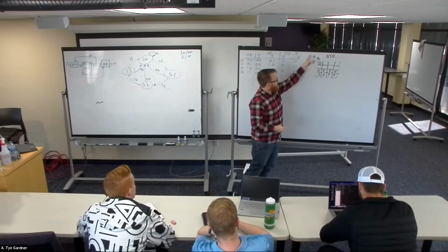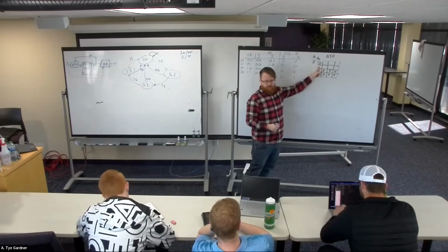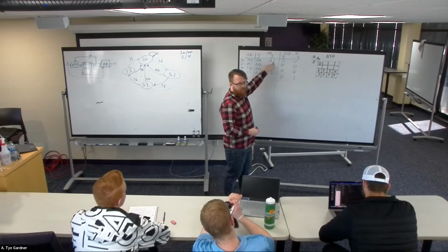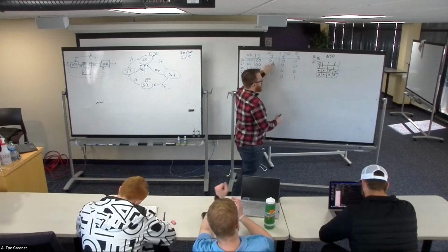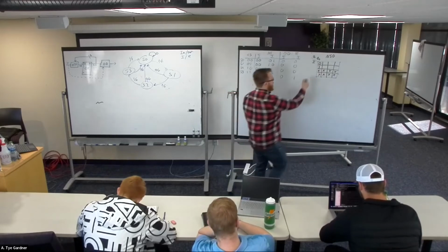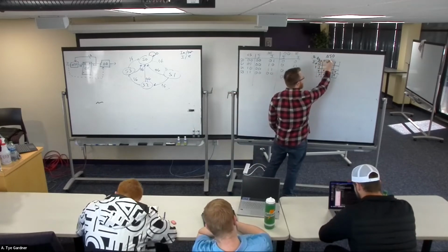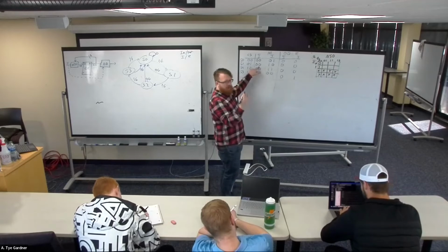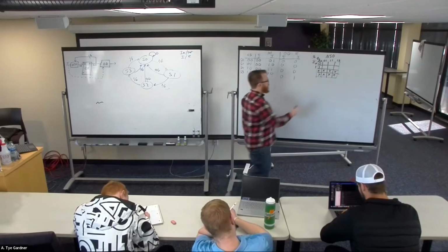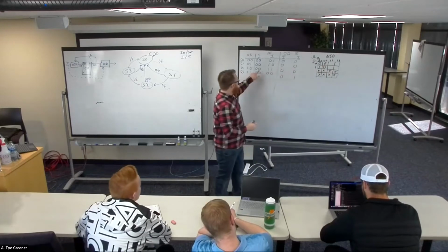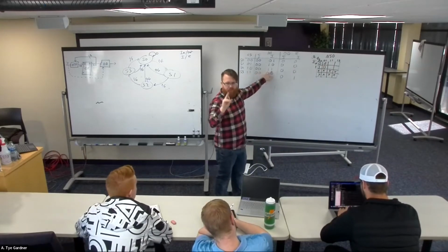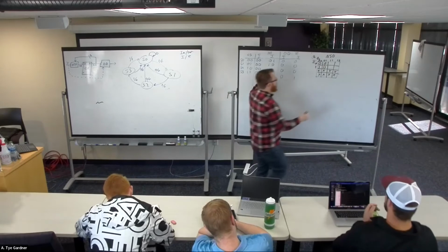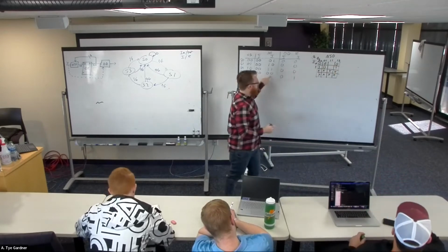Now, this square is state 0, right? For 0, 0, 1. 0, 0, 1. Right, because this is I is 0, I is 1. This is 0, 0, 0, 1, 1, 1, 1, 0. Then I say, well, if I'm in state 1, which is just the next column over, then it's 0, 0. Next one, the 1, 0, 0, 1, but remember, we flipped the columns of the K-map because we need to maintain logic adjacency. And lastly, 0, 0.